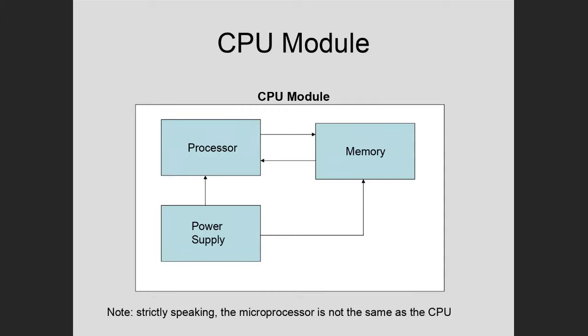Your device has to have enough intelligence to bring the operating system up and load it into RAM. And the only way to do that is to already have some kind of instructions stored on how to boot the system up and move the operating system from the hard drive to RAM so you can use it. The microprocessor uses RAM directly. So whatever you want the microprocessor to operate on, you've got to have in RAM. So you turn the cell phone on, you turn the computer on. The way it knows how to boot up is a small program in ROM, which doesn't need any power to store those instructions, to give the device enough instructions to bring the operating system up to RAM. And now you've got a computer, now you've got a cell phone, or whatever digital device you're using.